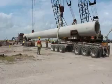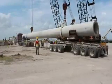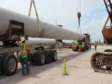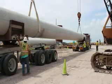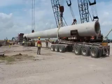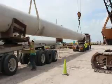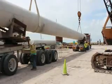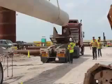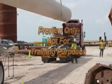Once the rigging is set, do a trial lift. Take load up about a foot. Confirm the sling can support the weight, the load is centered, and the crane can hold the weight with brake power only. Check for any load swinging or tipping. If the load seems out of balance, set it down and re-hitch it. Check for loose items such as screws and small tools, which could fall and strike workers below once load is lifted. Everyone should be clear of the lift area before the lift signal is given.